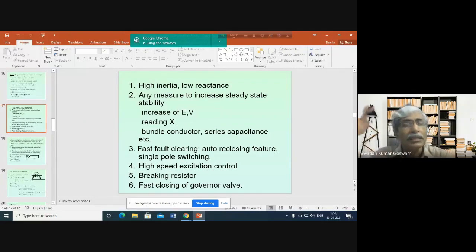In AC, these are not that fast, because in AC you have to use the auto transformer and the phase shifters. These are required for control of power flow. But in DC, this may be obtained with the help of converter operation, and converter control is very fast. That's why when a high voltage DC transmission system is used, power flow control may be employed very fast. Therefore, the transient stability problem may also be improved by using an HVDC transmission system.